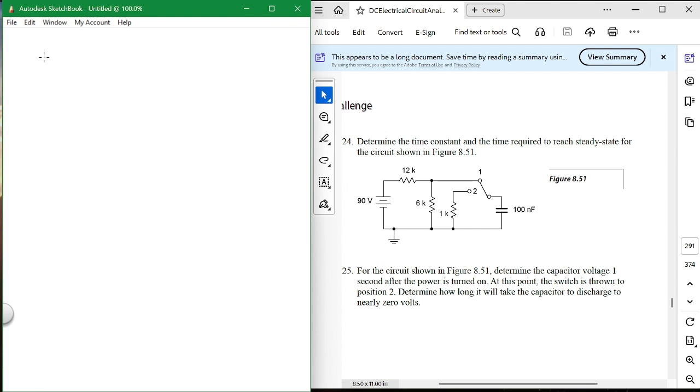So when a motor's contactor opens, current can't stop immediately. It jumps across, and every time you open and close that contact, there are electrons that jump across, and they take with them copper.